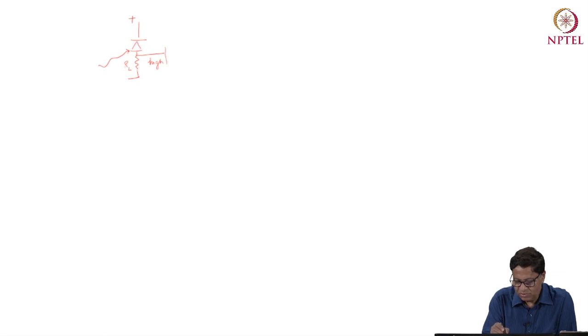Before you give it to the next circuitry, you use some sort of transimpedance amplifier, which changes the input high impedance to low impedance. So what you get is sort of low impedance, and then you give this to some sort of amplifier and you collect it here. Say, let me write this as A.